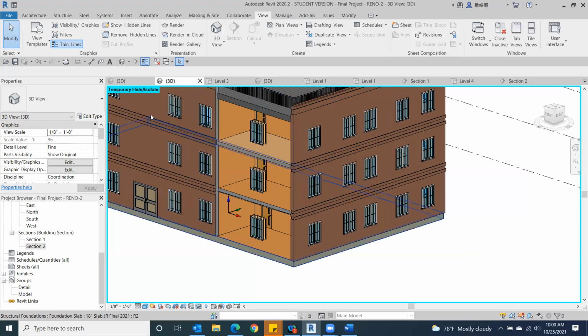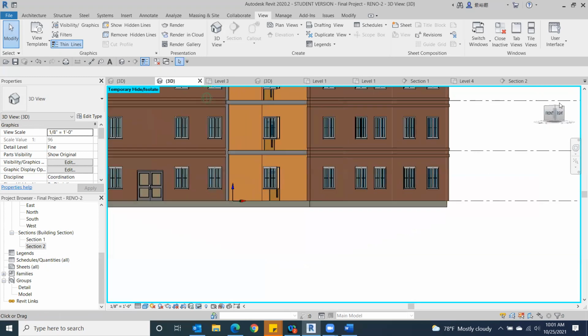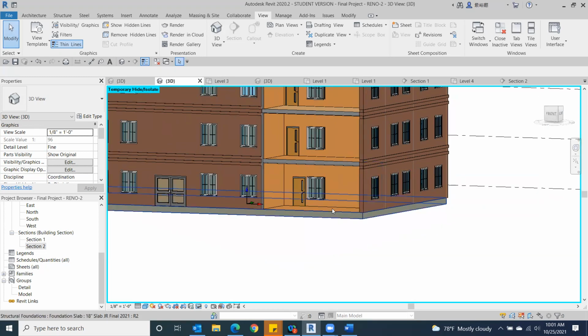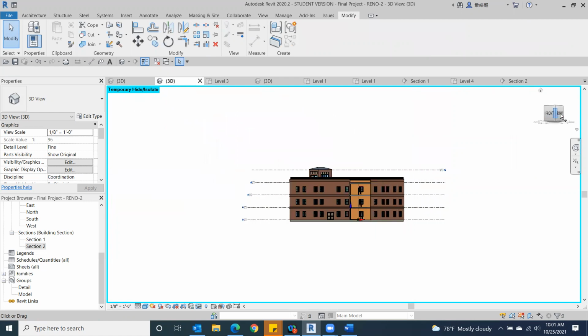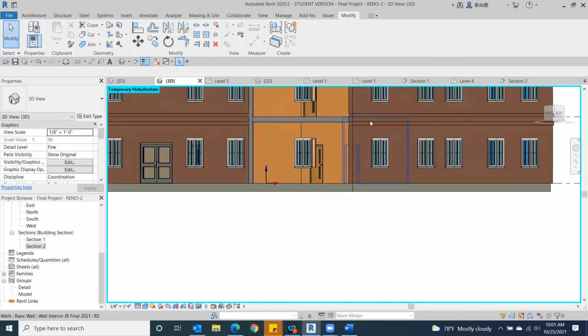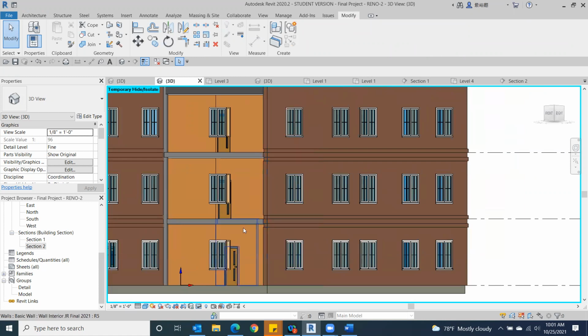So just the way you can split things vertically, we can split these walls horizontally, so you can have different floor colors on each floor. The first floor doesn't have to match the second floor. So remember to do that. We want to go ahead and jump to our modify tab. Let's do an angle view for this one so I can get that corner that I want. Let's say I want to split this between the first floor and the second floor. Same tool, same process.